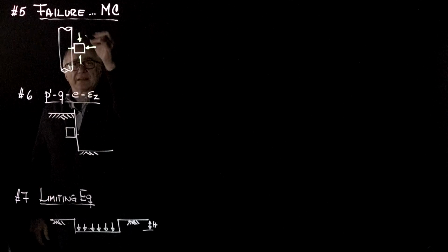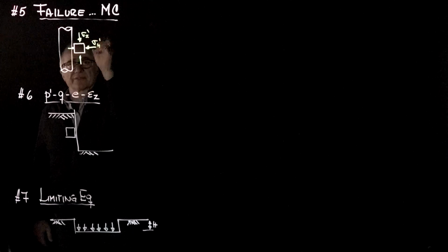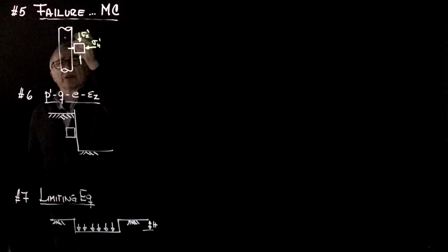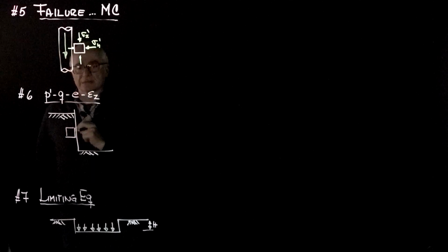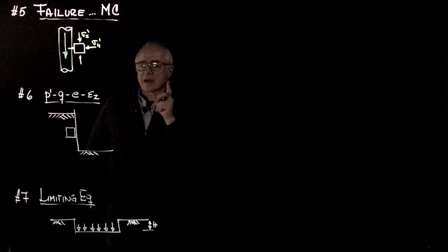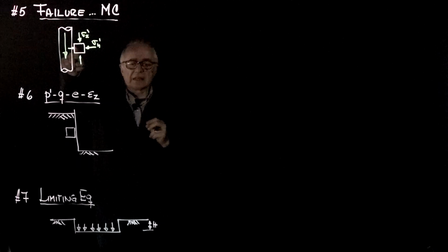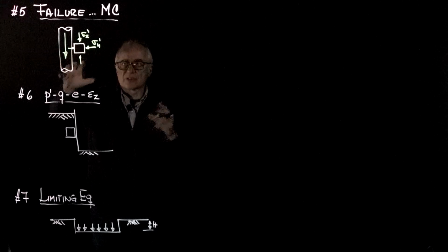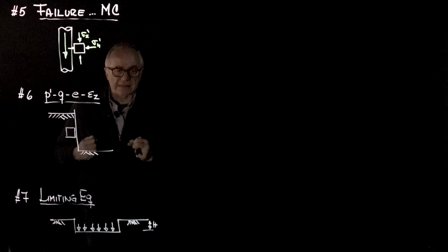And so the system has a certain sigma z and sigma horizontal effective, and we are going to load the pile, which is going to cause shear on that element. The question is, how much shear can the element resist, because that will contribute to the shaft resistance of the pile.